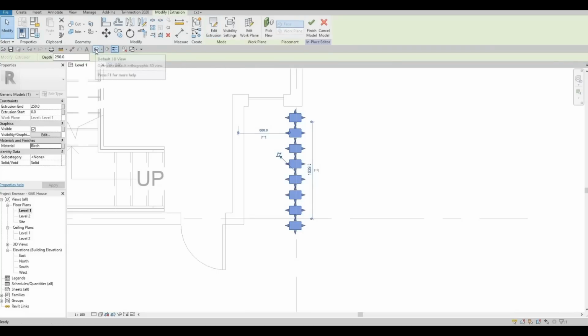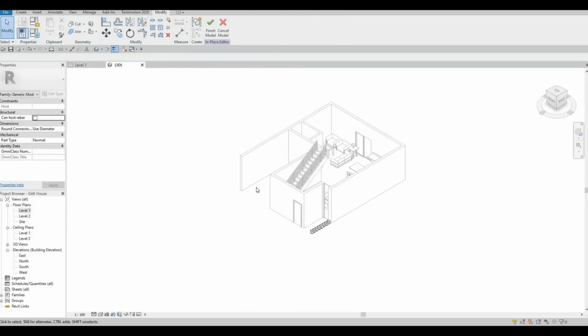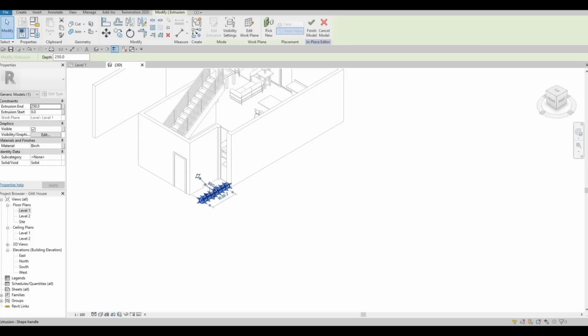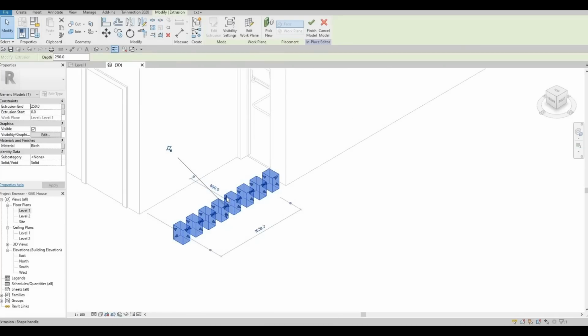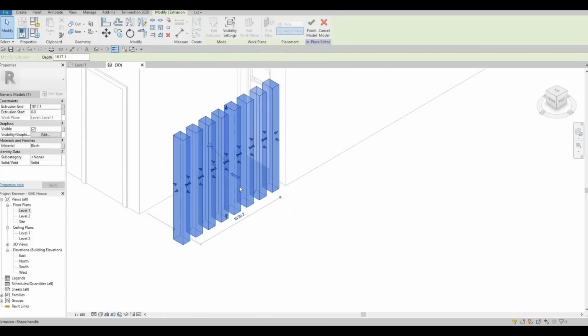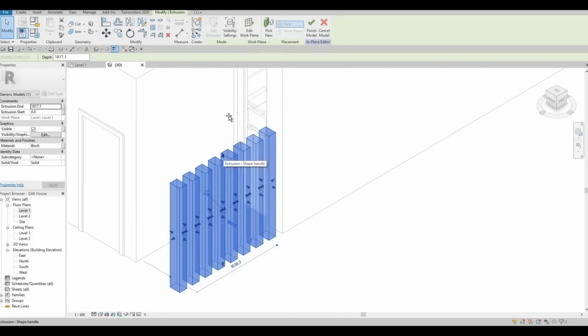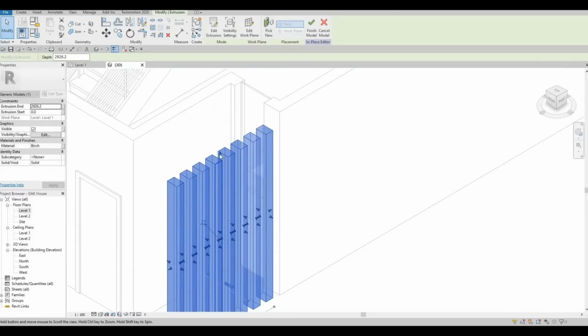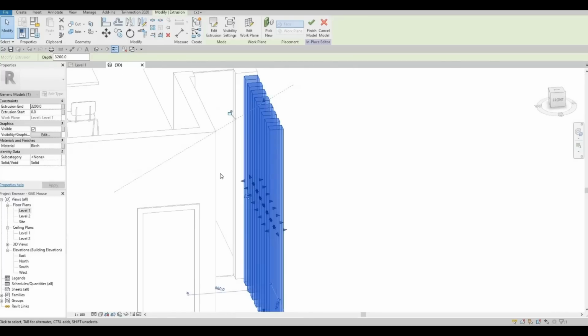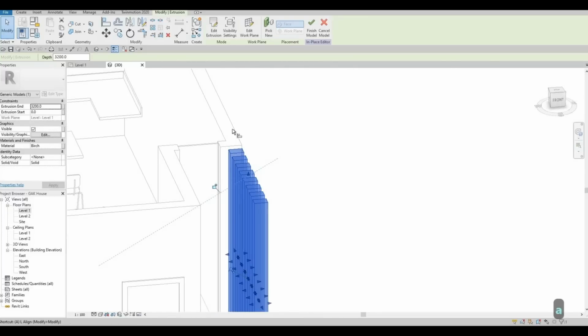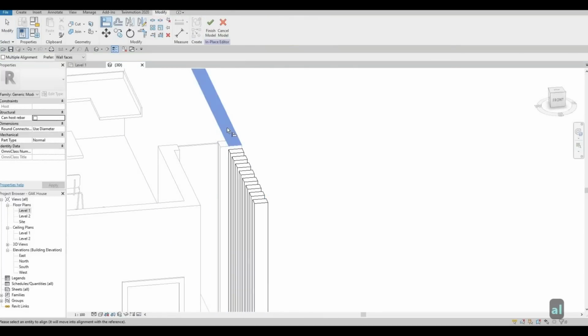And then we could look at 3D so that we could extrude it further manually. So here I'm just picking up this one or extruding it from the arrow. So like that. You can also use align, so AL, and then align it at the top of this plane and then here.